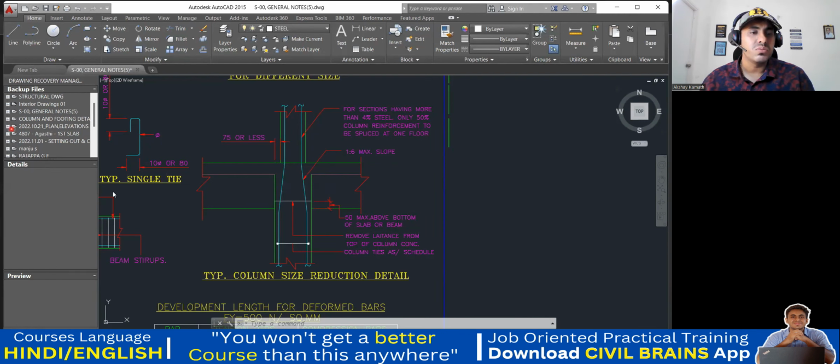Sometimes people don't follow this. They bring a bar and give too much slope like this, like this, and then take it inside like this. So it's telling you that you shouldn't do that. You need to maintain a 1:6 slope. Got it? Got an idea? So when you have a column of two different sizes and you're bringing a bar, this is how you are supposed to take care of it.